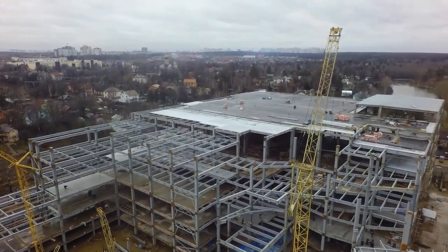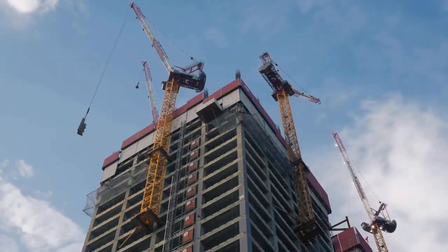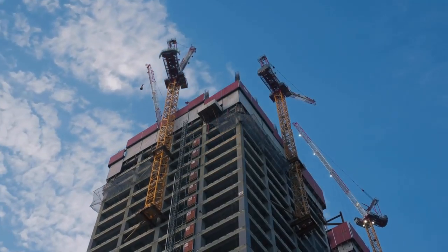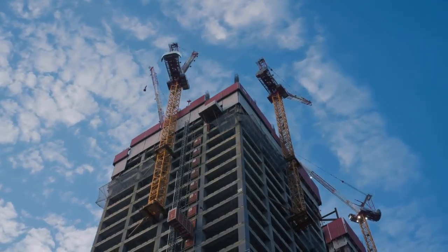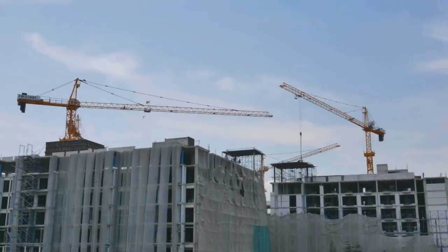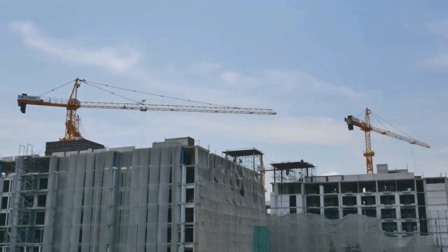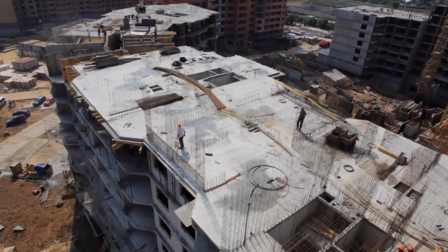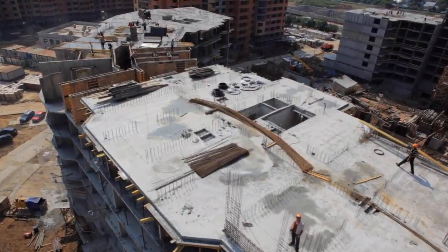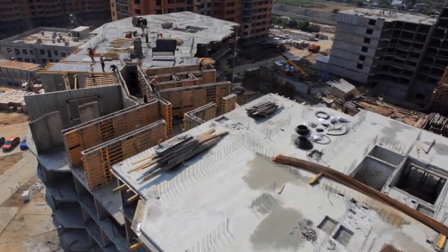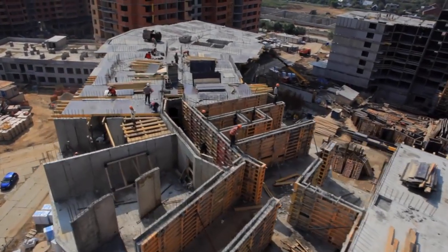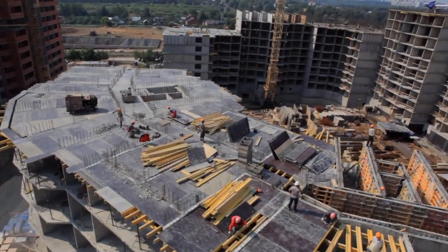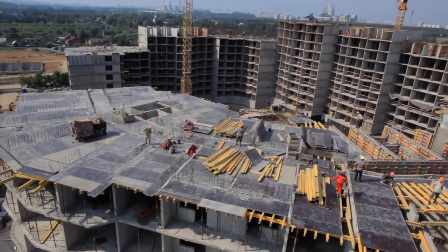It's a very important IS code for shuttering or formwork, or sometimes it's called falsework. And also IS 4990, that is for the plywood that we are using in the shuttering, that you need to follow. At the same time, we need to follow the IS code which is the mother of all IS codes, that is IS 456. For civil engineering, in any type of work, you need to follow this one. For aluminium formwork, the same IS code you need to follow for the design parameters and other things, that is IS 14687, and also IS 5525, IS 456, and the guidelines for the aluminium extrusion, aluminium form. That is the difference in the IS codes.